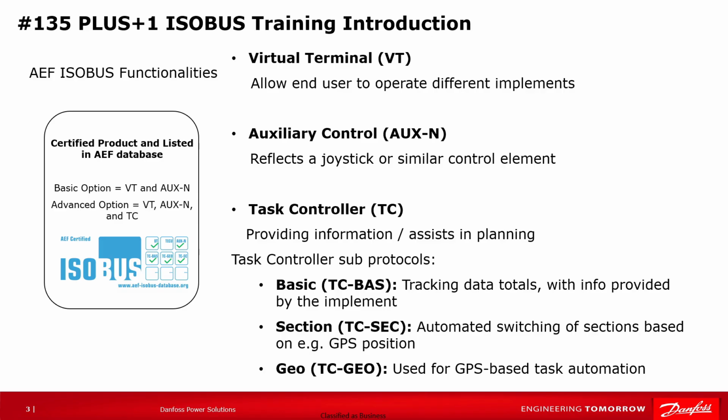Auxiliary Control, AUXN. This ISOBUS functionality often corresponds to a joystick or similar control, allowing finer control of implement functions. Note that both a new and an old version exist, and they're not cross-platform compatible. Danfoss only supports the new version.